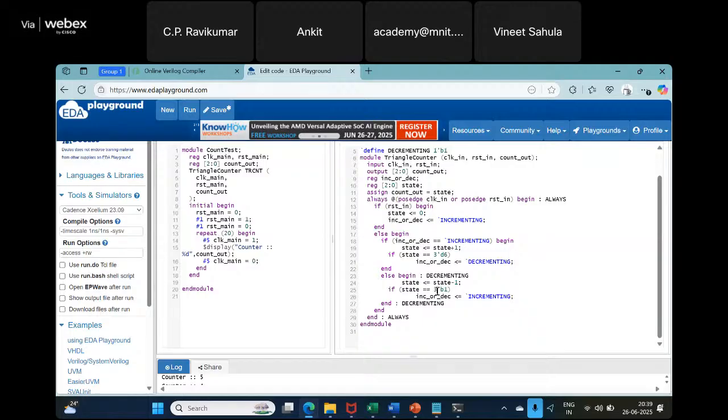Okay. So this taught us something. I think many people didn't know how to look at the number of states, etc. I hope that point is clear. And blocking and non-blocking also is something that you have to keep in mind. The non-blocking statement doesn't wait. So as soon as it comes to this, it doesn't wait for this. It will go to the next one. So that is the reason why we have to check for 6.